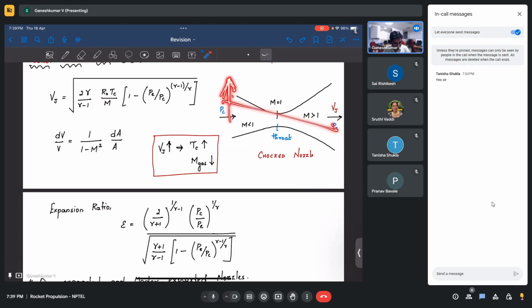The pressure gradient across the nozzle changes, right? So let's say I have 1 megapascal here, and I have 1 bar here, at that time it has choked here. Now if I increase it to 2 megapascal, the information will be reaching here, but the flow will not know this. So because of that, what happens? The mass flow rate will get fixed. The mass flow rate of the nozzle will get fixed.